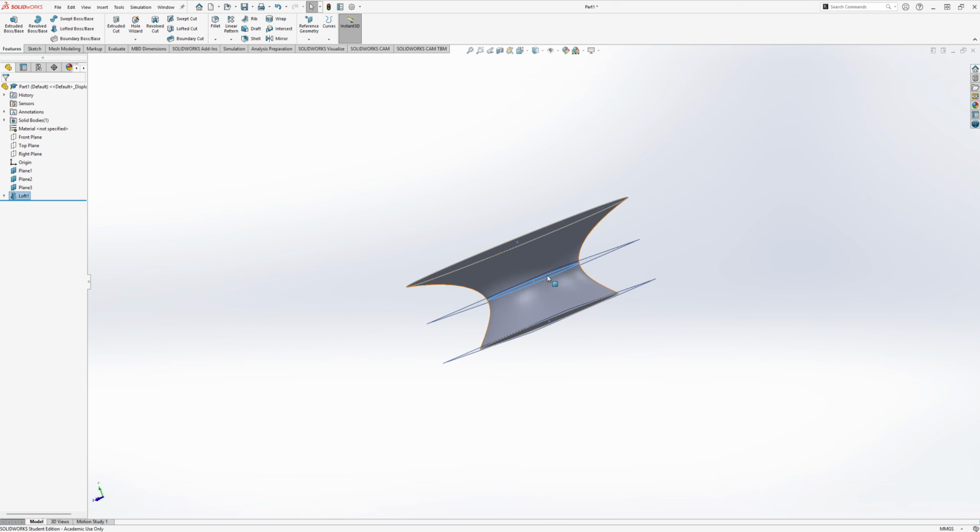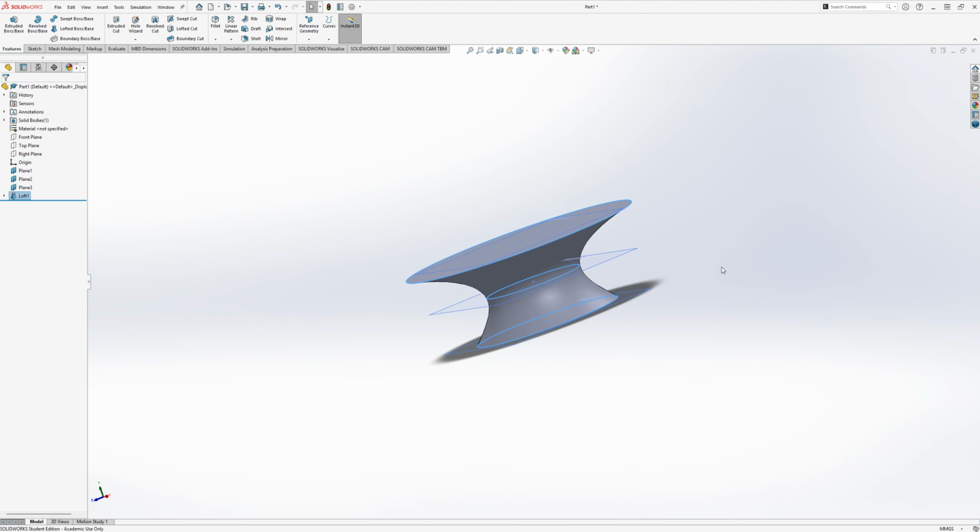It uses the outside perimeter of a sketch as a reference guide to form solid objects. Now you may be asking, what's the point of all this? Well, I just did a small project where I had to create chess pieces. It was extremely easy to create pieces such as bishops and pawns just using this lofted boss/base function.